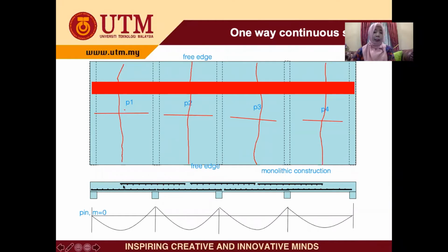So this is the steel arrangement. You need to understand the steel arrangement, since this is the maximum moment here. So we need steel here, main steel. So this is the main steel for the moment here. When you design, you get this main steel.